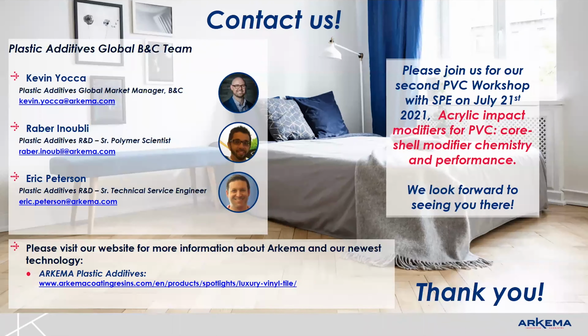Okay, next question. How does regrind affect the gelation of the PVC compound? Yeah, so that's a popular one. I think what you would find is that it's typically not helpful. The thing to remember about regrind is that it's already been processed through the main process once. In reality, because you're using regrind, I think 6 to 7 iterations of the material that have been processed exist within that regrind too.